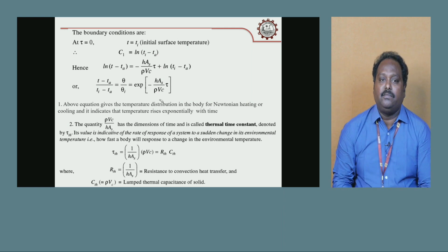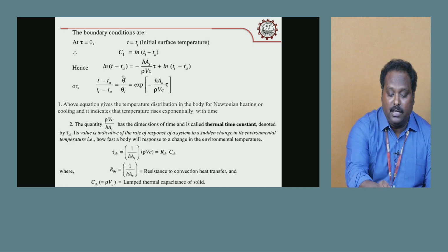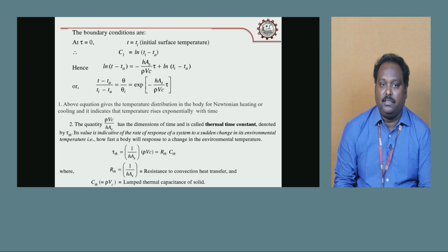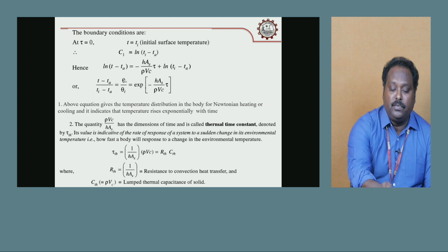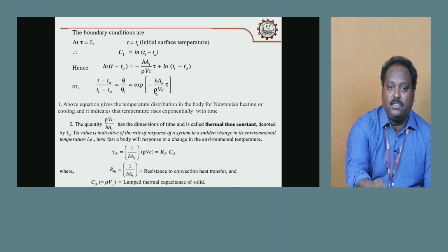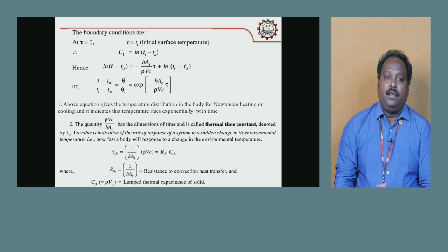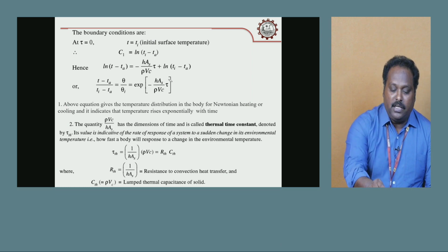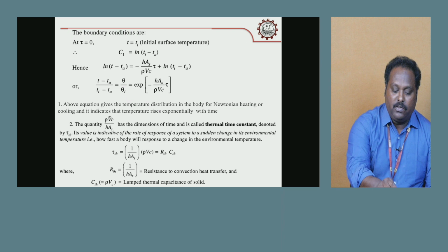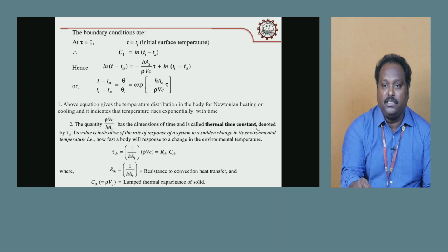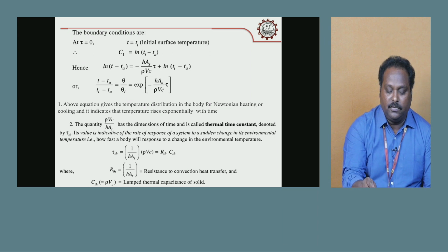This is the governing equation for lumped system analysis, when you assume the internal conductive resistance is negligible. The quantity rho V C by hA is called the thermal time constant.